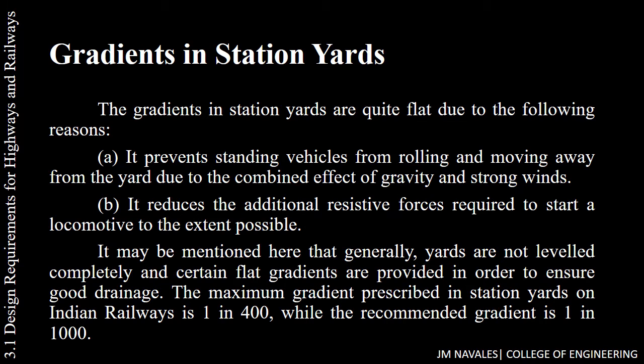It may be mentioned here that generally yards are not leveled completely and certain flat gradients are provided in order to ensure good drainage. The maximum gradient prescribed in station yards on Indian Railways is 1 in 400, while the recommended gradient is 1 in 1000.